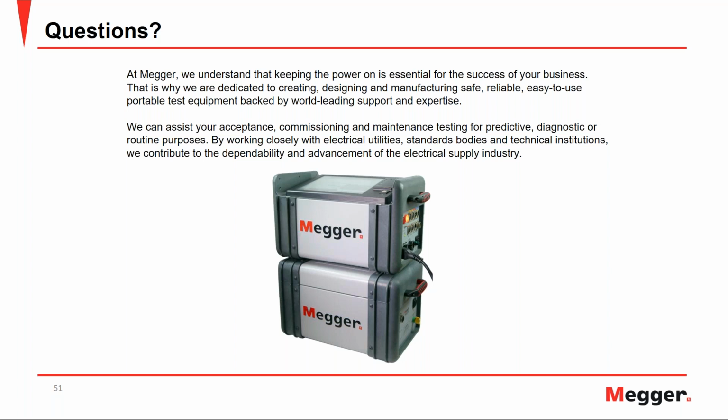And for dry type transformers, sometimes, depending upon the type of installation, it is recommended to perform a tip-up test. And tip-up test is exactly what the question is asking, where you increase the voltage in small increments and go all the way up to the rated voltage. And that test is very common for dry type transformers, rotating machinery like generators. People do the tip-up test all the time. And there is an IEEE standard available as well, which talks about how to perform a tip-up test.